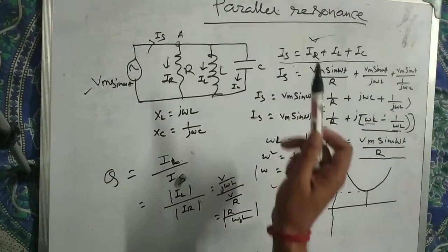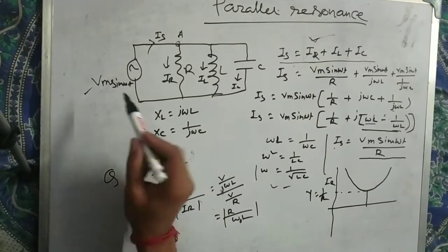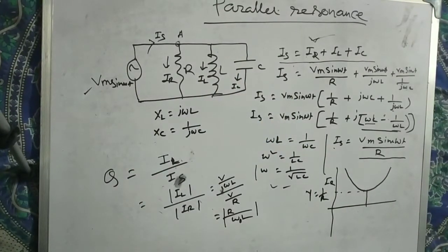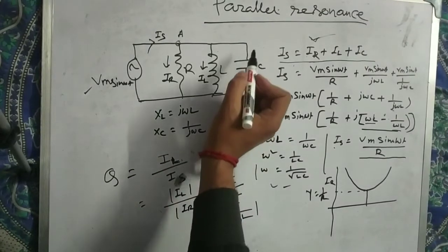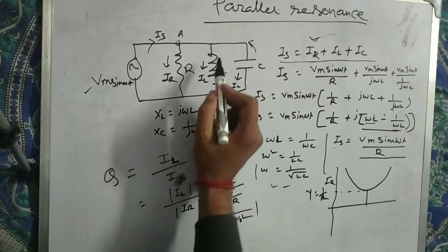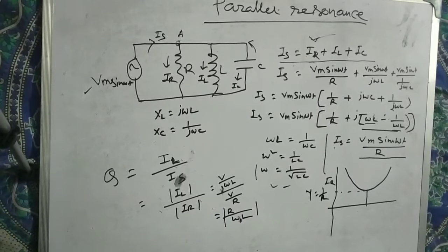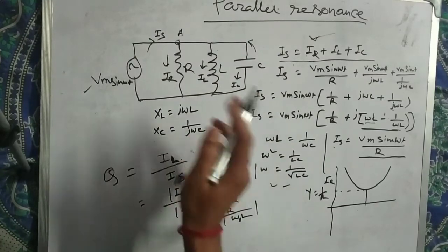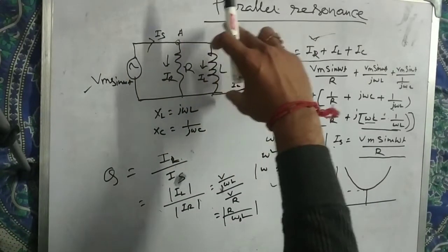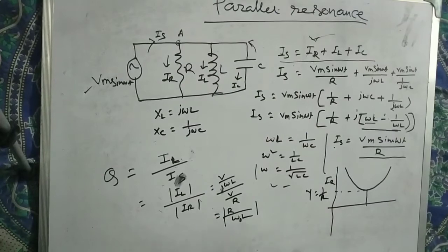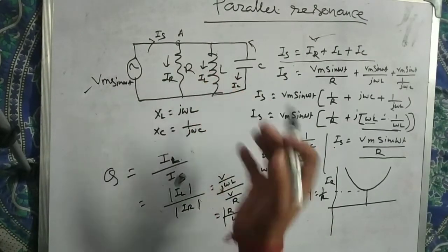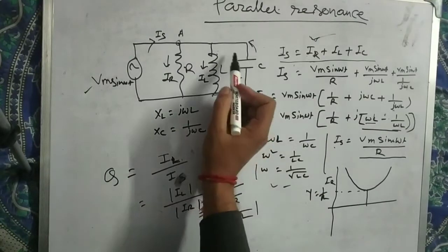And also we can derive that capacitor and inductor are reactive power elements. The capacitor always supplies reactive power, the inductor will absorb reactive power. So if we want to understand the resonance physically, the voltage across the inductor, capacitor and resistance are the same. So at resonance condition, the inductor and capacitor are not taking any power. So what is happening?